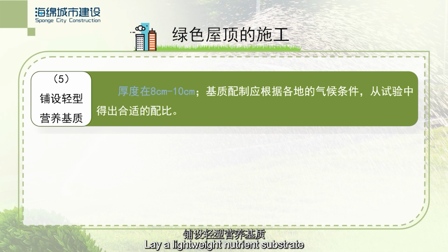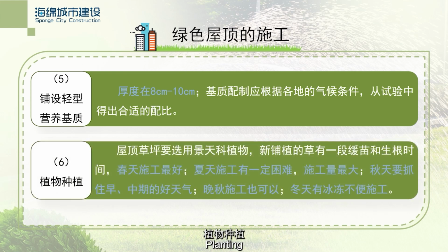Lay a lightweight nutrient substrate, 8 to 10 cm thick, tailored to local climate conditions, getting the appropriate ratio from the test. Planting. Use sedum plants for rooftop lawns.